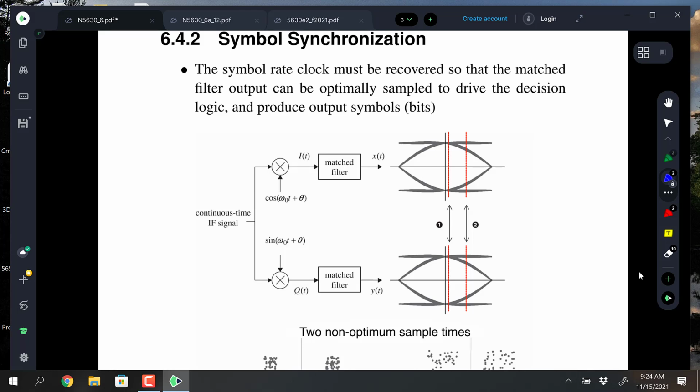If I would have made the symbols not occur synchronously, the 4th power loop can still get the carrier back without having samples at the correct location. I don't think that was obvious though, was it? I could have added some code in to do that if I'd wanted to, and I'm going to do that in the next example. So then the symbol synchronizing could happen afterwards. Symbol synchronization can happen either first or second as well.